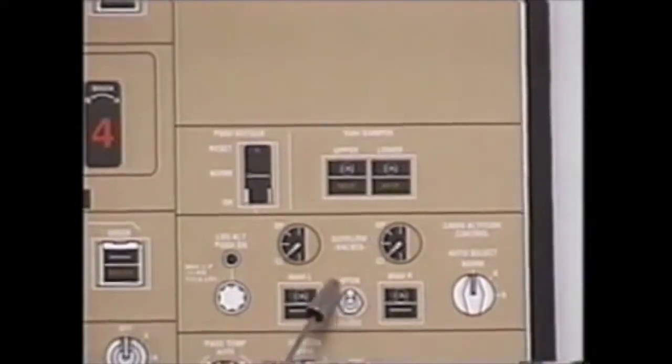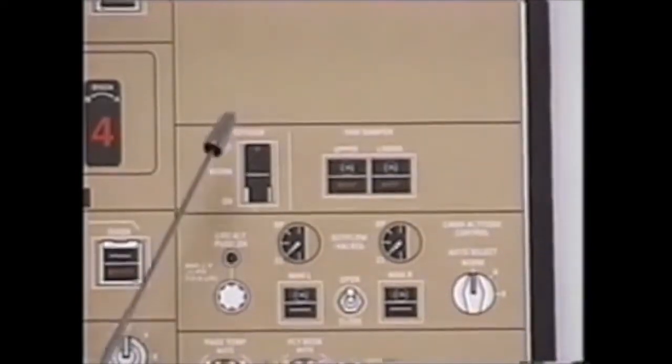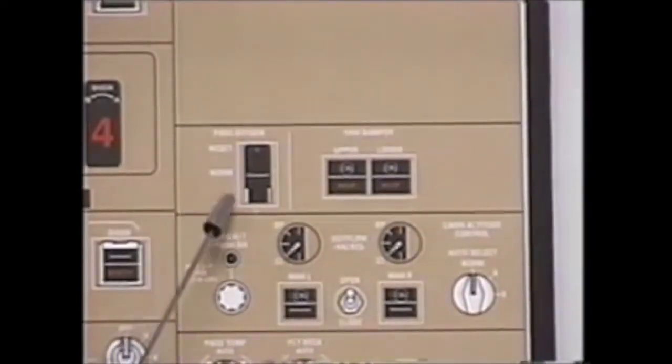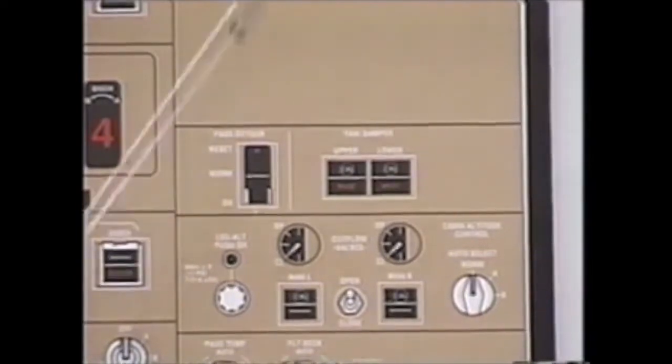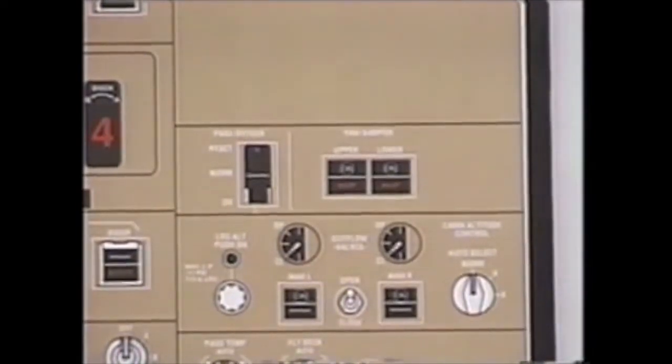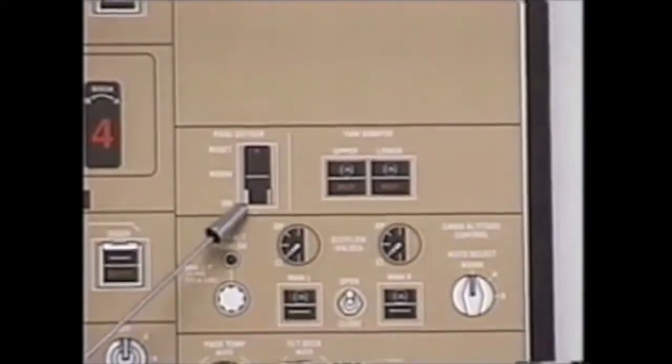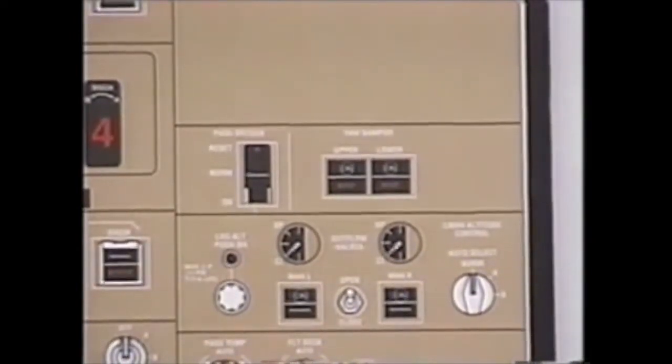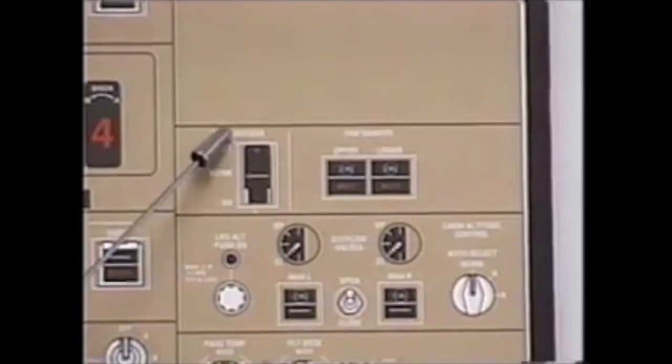Above your pressurization control panel is your oxygen control panel. It has a 3-position switch: norm, on, and reset. This is the only switch required to be safetied during the cockpit setups. That would put it in a norm position. In a norm position, whenever the cabin altitude exceeds 14,000 feet, the passenger oxygen system automatically activates. Regardless of cabin altitude, if you reach up and select the system to on, the system will activate regardless of pressure altitude. To reset the system, you must be below 12,000 feet of cabin altitude. Momentarily hold the switch to reset.